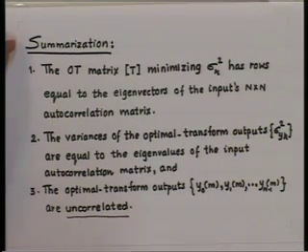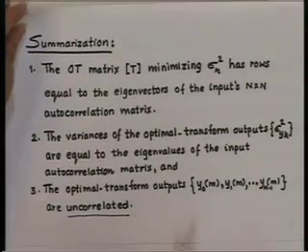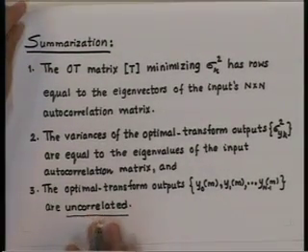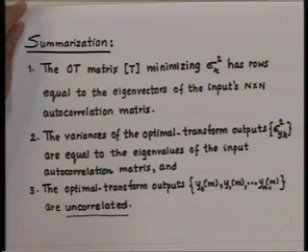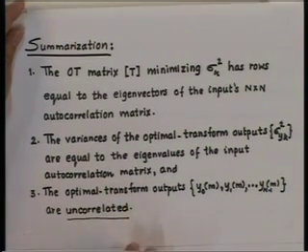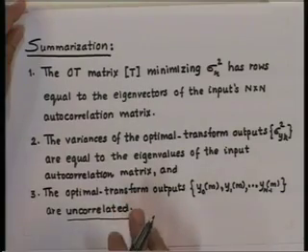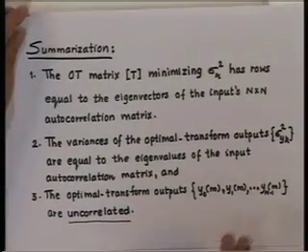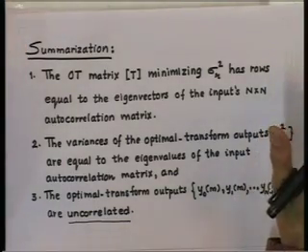This is a very important result. So, the presence of mutually uncorrelated transform coefficients supports our approach of quantizing each transform output independently of the others. Now, if we have the source output vectors as Gaussian, then the transform outputs will also be Gaussian, and the KLT will decorrelate these components, and for the Gaussian case decorrelation also implies independence.